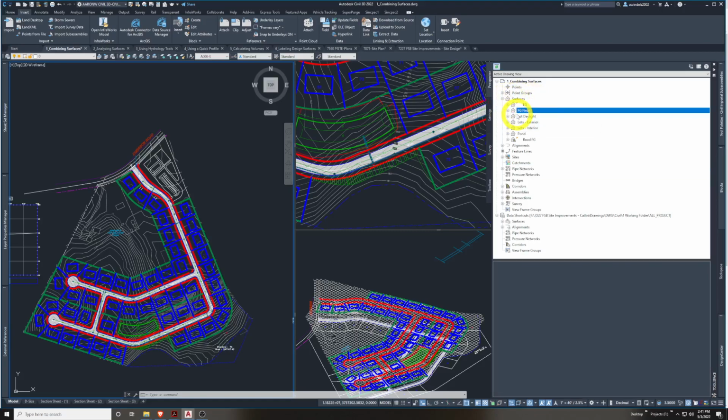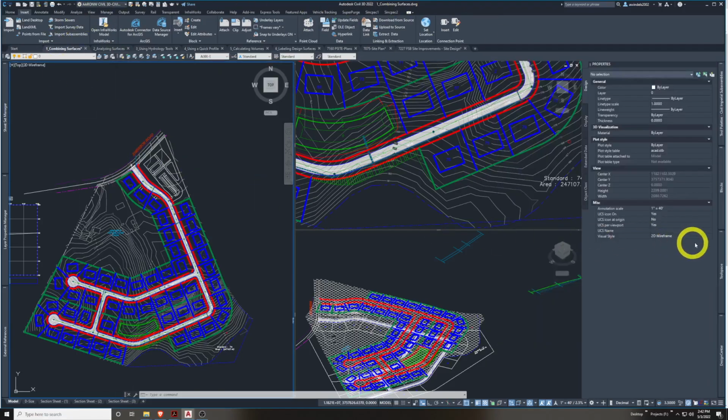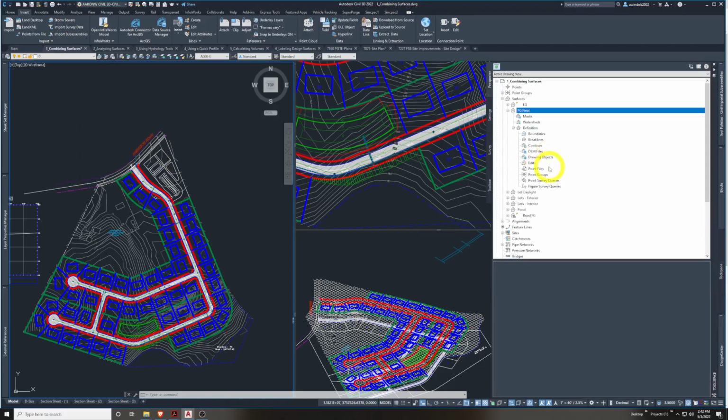And we're going to stay in the tool space tree here to get you a little more familiar with the tree. I know we've been bopping in here a little bit this semester, but not quite as much as you've been learning a lot more about the ribbon in general. We'll go into edits. So a surface has certain definitions. We remember a little bit from chapters 3 and 4 how to build it. Certain data builds it: files from the background, elevated contours, break lines, could be a variety of objects that make a break line, different drawing objects, points, lines, text, various other things we won't go into here.